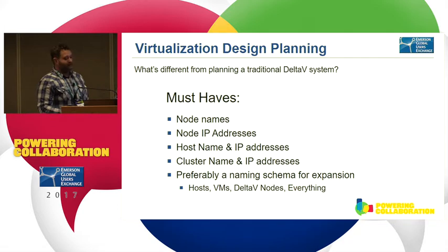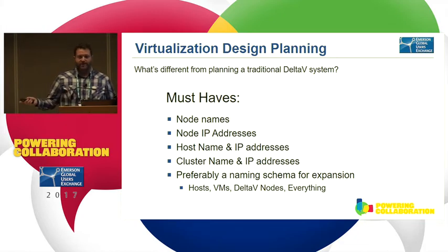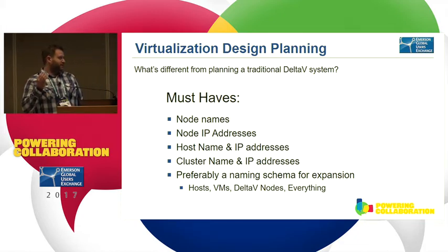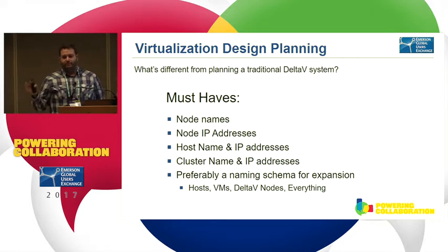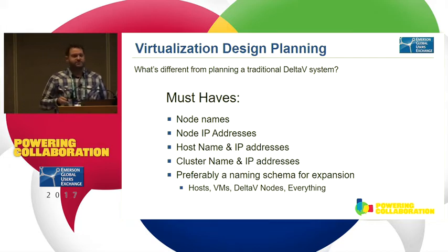So stepping back a moment to the system design, how is a virtual system different than a normal DeltaV system? You might not necessarily know what you're going to call everything when you start designing a DeltaV system. You know you have a Pro Plus, you know you have an app station. But if you want to wind up with a virtual system that's great, these are the things that you absolutely have to have going in before you even start planning. You've got to know what you're going to name everything. You've got to know IP addresses. You've got to know cluster names, IP addresses for the cluster, all these technical details that we wouldn't necessarily think about during a physical design.